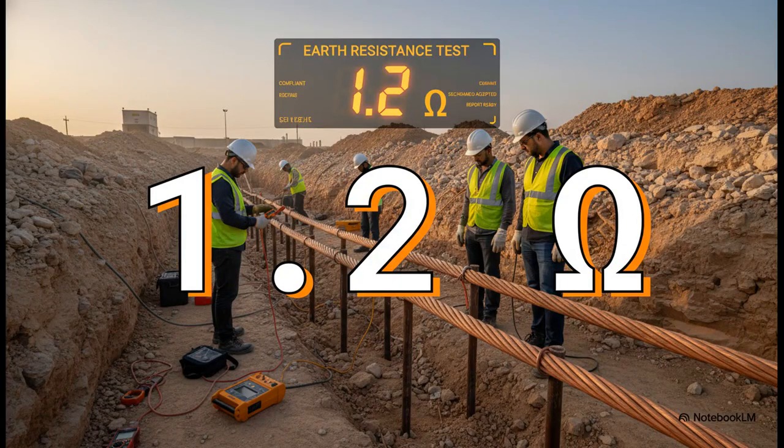Now let's flip that. You've installed the earthing grid exactly as designed. The test is done again. The new reading? 1.2 ohms. Perfect. That is a safe, compliant value that will be accepted by SEC and Aramco inspectors without any issues. And your signed earth resistance test report is the proof you need.